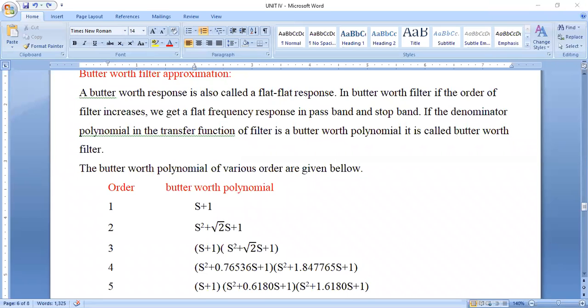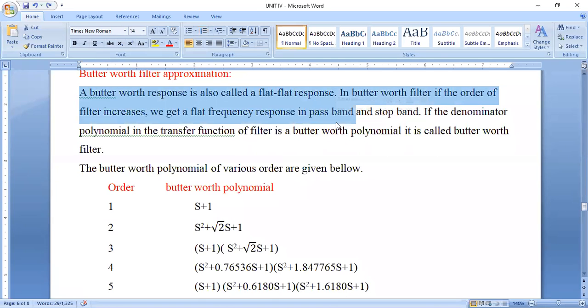So the Butterworth filter has a simple circuit and it has a flat response characteristic. The circuit is simple, but the internal circuit design depends upon the order specification. If it is a first order filter, only a single resistance and a single capacitance are connected, and if it is a second order filter, we use more resistances and capacitances, increasing with respect to the order of the filter.